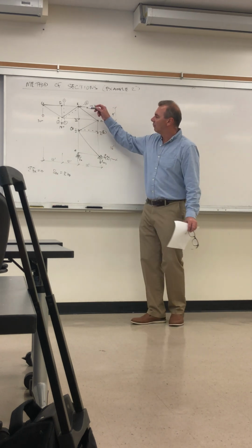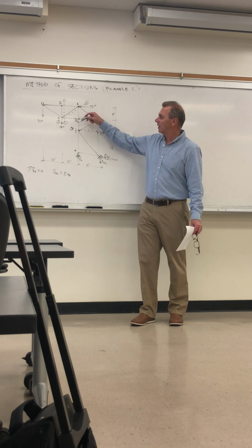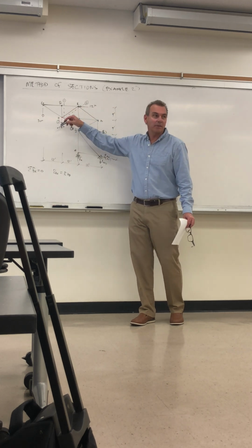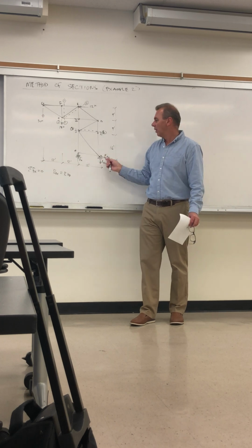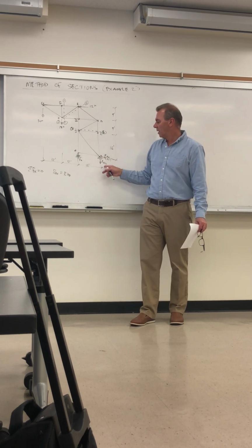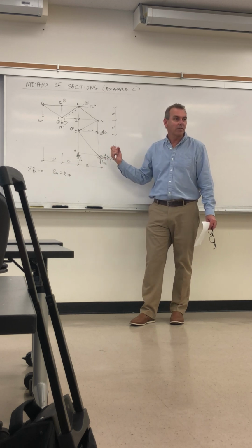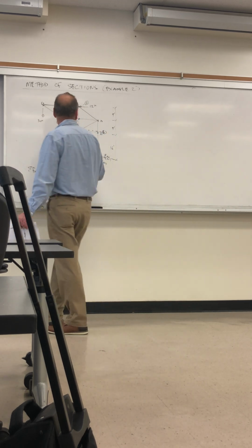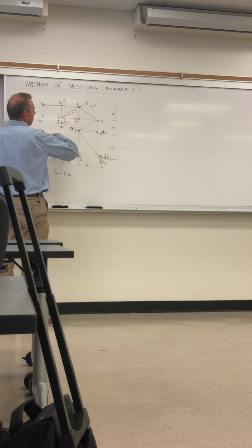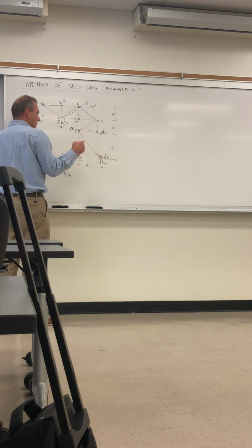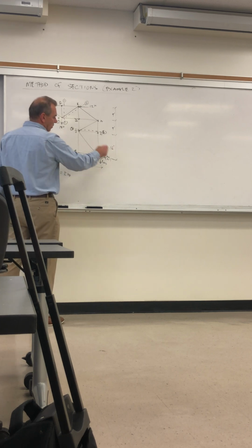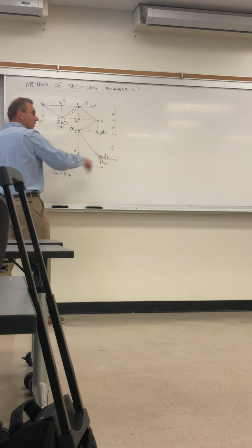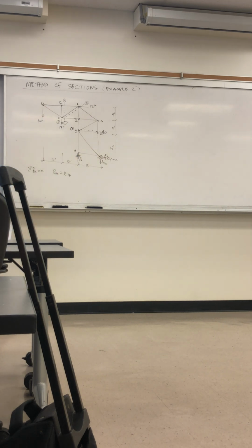Everything applying a force on the structure, the 12 kips to the left and the 18 and 30 kips down, all of them are tending to have this thing rotate about A, wanting to lift up. So this reaction is holding it down, and you can see by taking moments about A that all of these applied forces are causing, taking a look at an axis coming out of the page, counterclockwise movement. And so this reaction times this distance has to be in that way, that provides a countering clockwise movement, right? When you're looking back.